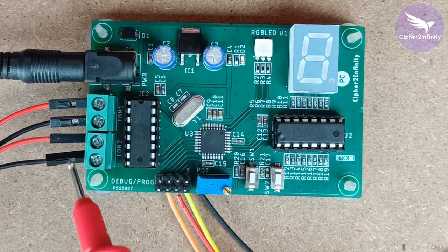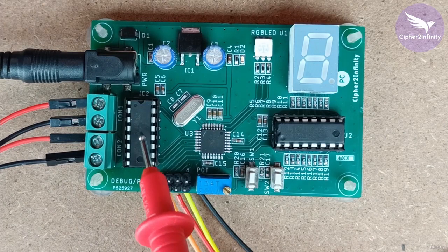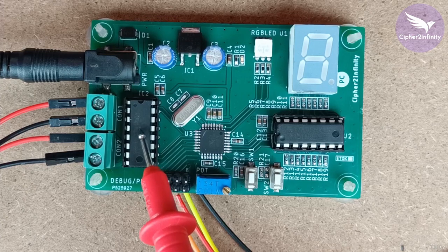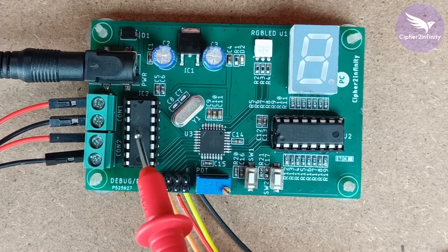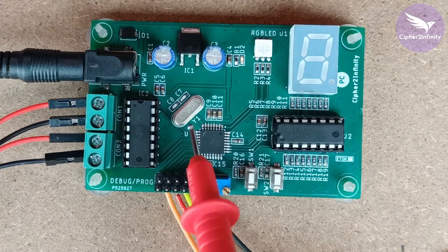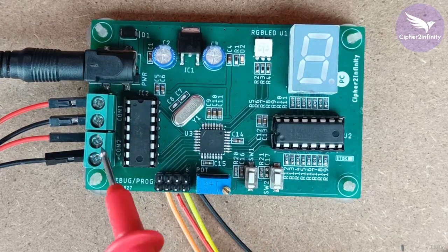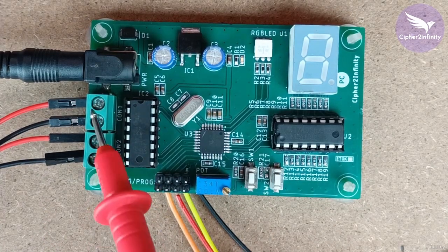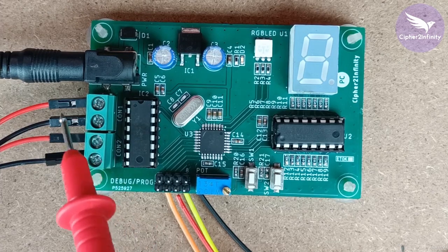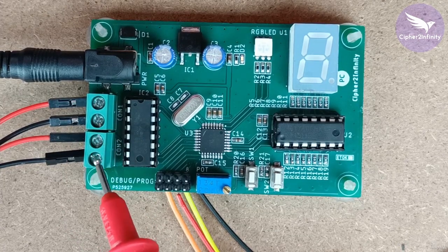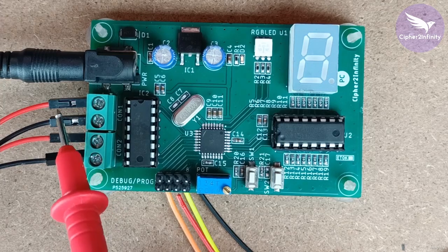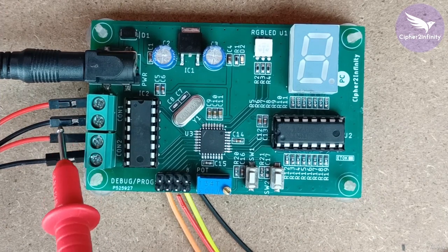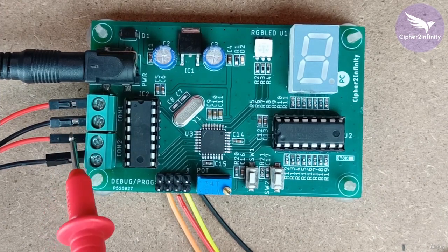Okay, so I hope that you got every single thing that we discussed regarding the testing and troubleshooting of L293D IC. Okay, and one more thing that I want to tell you here is there could be a problem with the motors as well. Okay, so it might happen that everything is perfectly fine on the motor driver section, but there might be a problem with the motors that we have connected on the terminal blocks. So what you can do, simply you can remove the motors from the terminal block and individually check the motor. You can directly connect these two terminals to the plus 12 volt, or you can connect these two terminals directly to your power supply. In the same way you have to do it for the second motor.